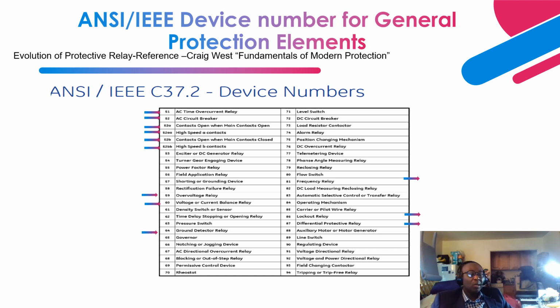Let's say you have a differential protection that activates. That differential relay is wired to a lockout relay. The lockout relay has a lot of contacts. It trips the unit breaker, then it trips the turbine side steam valves, then it trips the field breaker. So basically, what a lockout relay does is it has that multiplying contact to trip other sources that are supposed to be tripped in addition to tripping the unit breaker.